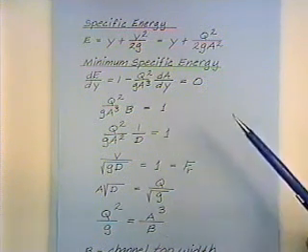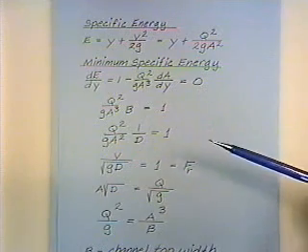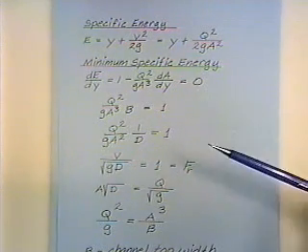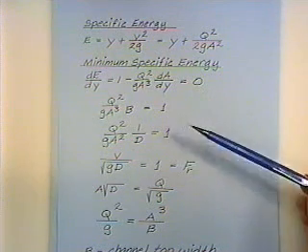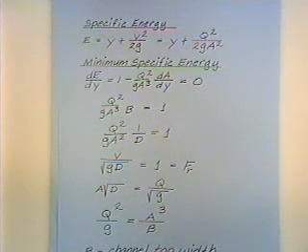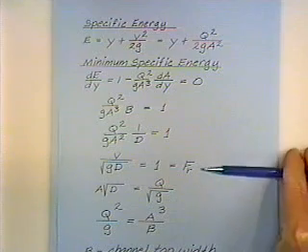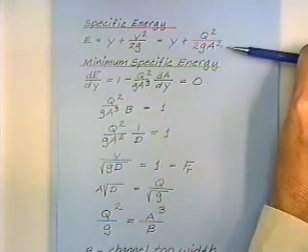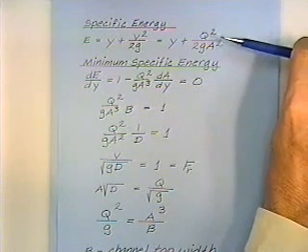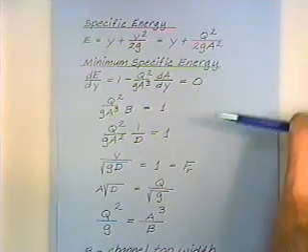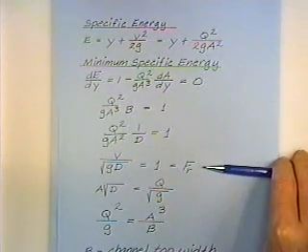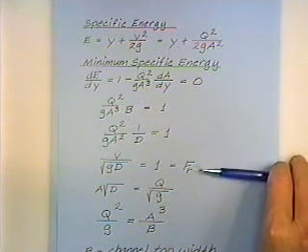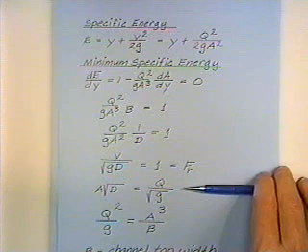And so we do that. We're just going through a quick derivation here. Take the derivative with respect to y, and then set that equal to 0, and do some algebraic manipulations. And what we've just proved to you is that minimizing the specific energy results in the Froude number being equal to 1. And then you can rearrange that a bit and get this equation.